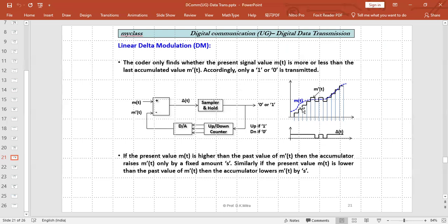It could be 1 millivolt, could be 10 millivolt. That is as per the design. So, coming here in this line, it finds that the blue dotted line is still more than the last signal, so it takes one step higher, right? The output of the sample and hold circuit goes up by one defined step.